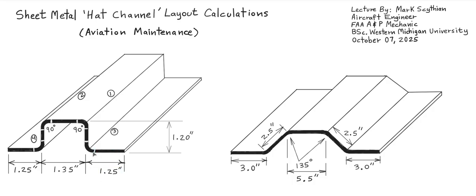We then add that to the bend allowance, the actual circumferential metal derived of a circle, its circumferential distance. This is known as the bend allowance. Then we would add this to the flat 2, bend allowance 2, flat 3, bend allowance 3, flat 4, bend allowance 4, and then flat 5. But we're going to start from the left and go right here.